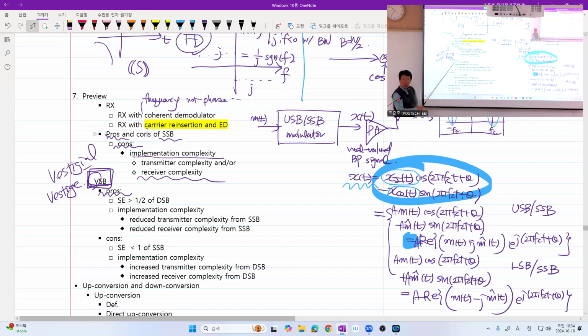Spectral efficiency of double sideband is 1/2, right? Now, you have somehow, not every, but some part of the unwanted sideband gone, which means that your bandwidth is greater than B, but less than 2B, which means that its spectral efficiency is between those of single sideband and double sideband. So in that sense, you save the frequency. You increase the spectral efficiency. Got it? That is good.